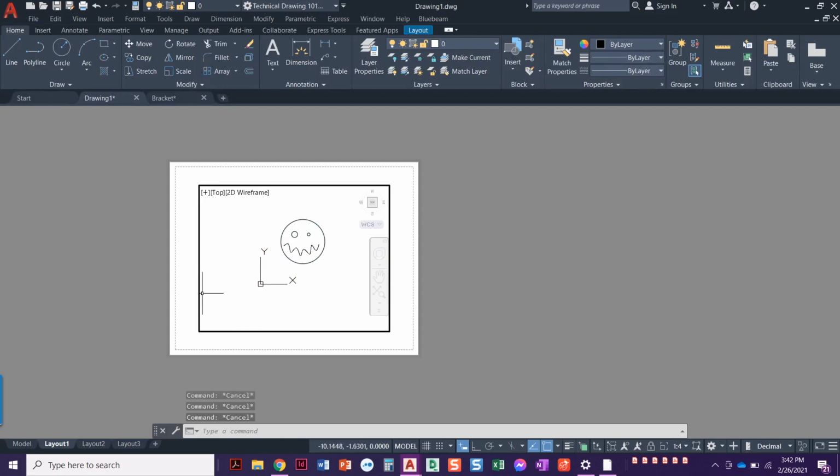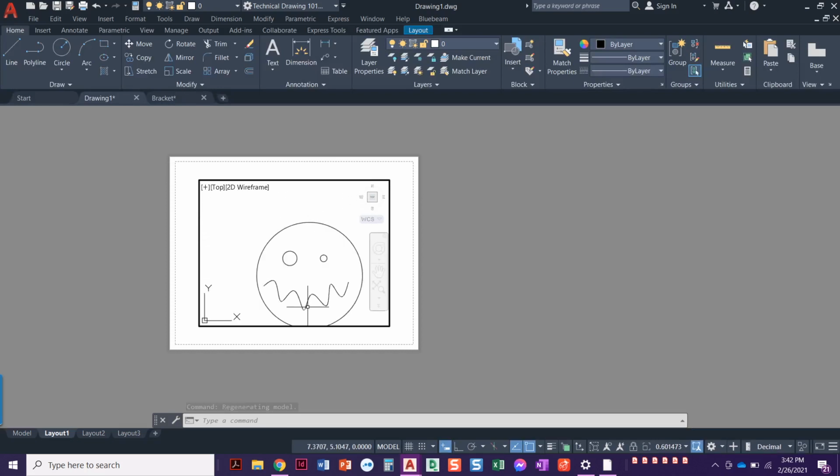that model tab. I can no longer select the viewport. I can't click on that rectangle. I can't click on the viewport because I've really jumped through that window. Now I'm outside. I'm not standing in the room anymore. But from here, if I roll my wheel in and out, I'm zooming. I can pan. This is where I was saying, don't worry about it not being centered. I can pan just like I normally can.